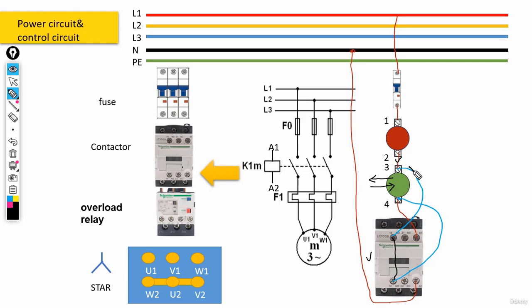It moves all the way from here, through here to the contactor, also through the contacts, and it continues following the path all the way to A1 terminal in the contactor. And as a result of this, the contactor would stay on. So we somehow made this permanent. We don't need to use our finger for pushing and pulling every time.